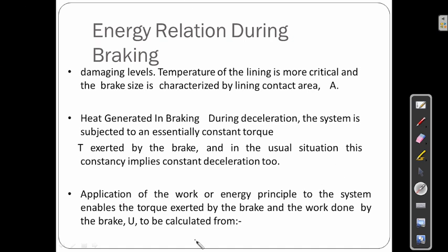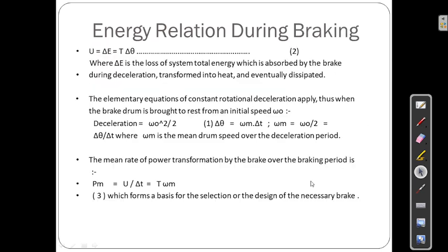Then the application of the work-energy principle enables the torque exerted by the brake and the work done by the brake to be calculated from U = ΔE = TΔθ. This is the formula, where ΔE is the loss of system total energy, which is absorbed by the brake during the deceleration, transformed into heat and eventually dissipated.